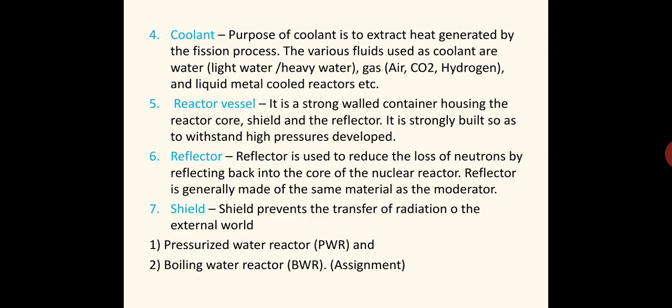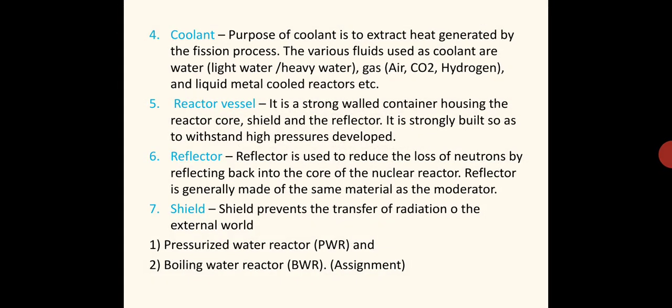The various fluids used as coolant are water, light water or heavy water, and gas. If it is gas, then air, CO2, hydrogen, and liquid metal cooled reactors. All these are commonly used coolants. The purpose of the coolant is to carry the heat produced by the fission reaction inside the reactor to outside the reactor, and finally, passing through the heat exchanger, it is given to the water, so that steam is produced. After giving away heat, the cold coolant is circulated back to the reactor. So the heat energy produced inside the reactor is carried by the coolant to outside the reactor. That is the function of the coolant.